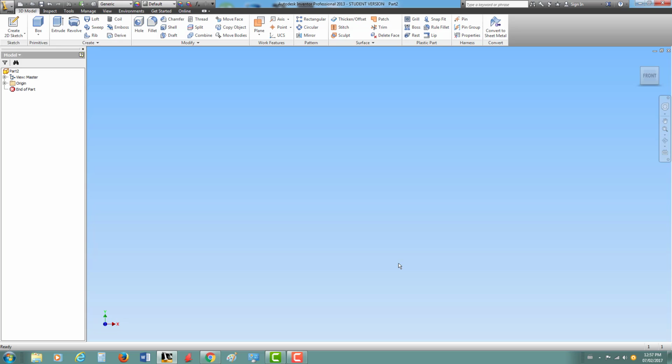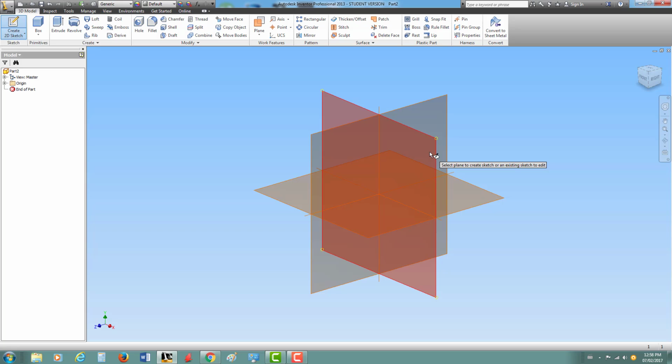which to work within. The first thing we're going to do is, Inventor always needs you to draw a 2D version or a 2D face of a 3D object before you can make the whole 3D object. So we're going to start with our wheel. If you think about a wheel, it's essentially a cylinder, and one of the faces is a circle. So that's actually the 2D drawing we're going to start with.